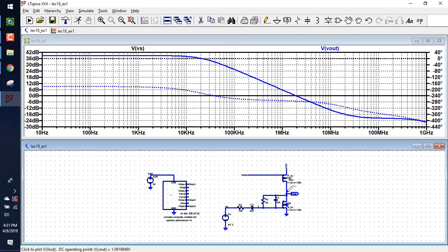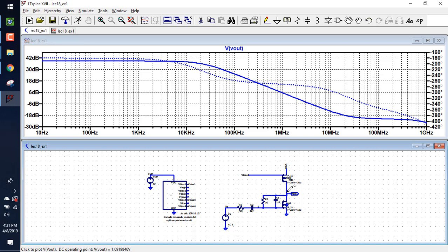Now here's my output. And then tell me where is the 0, and tell me how to identify that. It's where it starts to flatten out, right? It's rolling off. It hits the 0. The 0 says, hey, stop rolling off, start going back up. So it stops rolling off and starts going back up. So if I look, that's right around in here. What is this frequency right around in here? About 20 megahertz. What did I calculate? 23 megahertz.